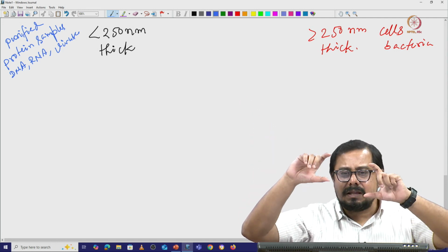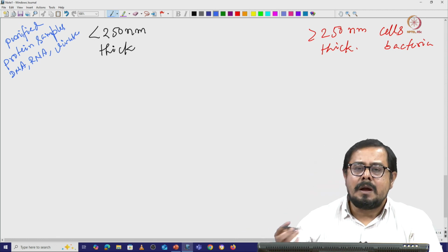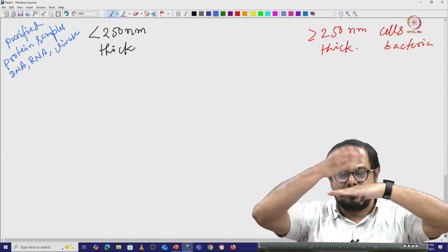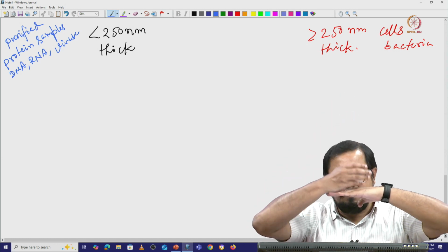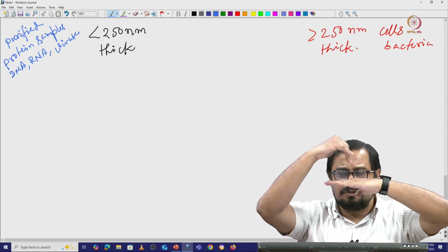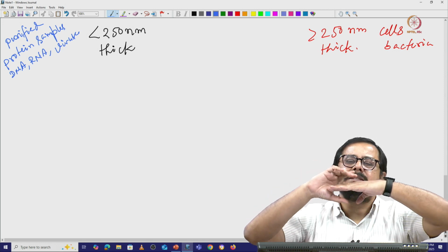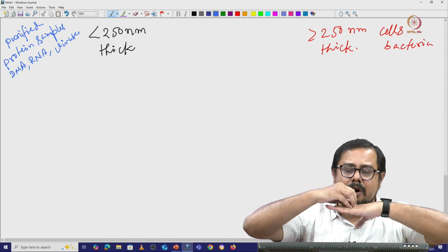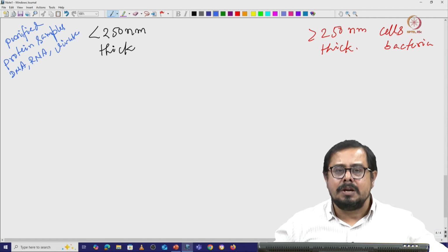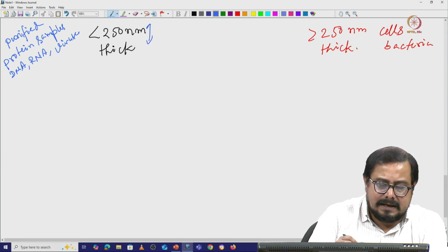So we are just recording the backscattered or secondary electrons for the scanning electron microscope. But for the transmission electron microscope, the electron beam is going through the sample, and when it goes through the sample, we are imaging. So the electron beam needs to transmit. If it cannot transmit through the sample, if the thickness is very high, it is going to block everything and we cannot see anything on the screen. That is the reason thickness is a very important part here.